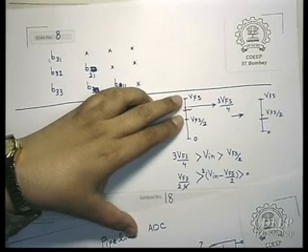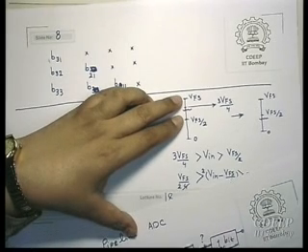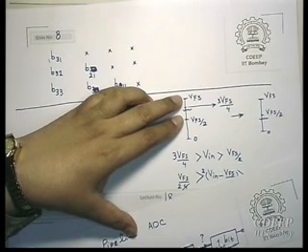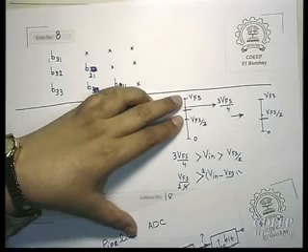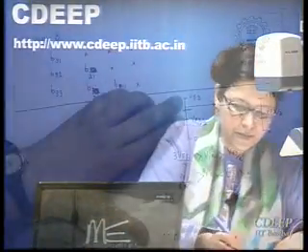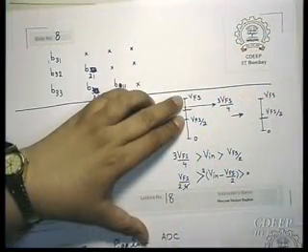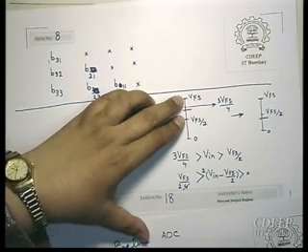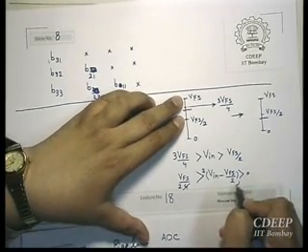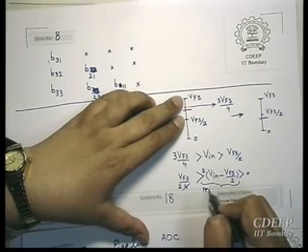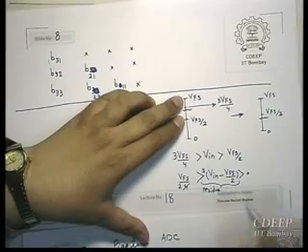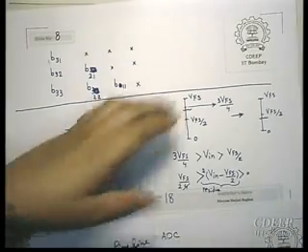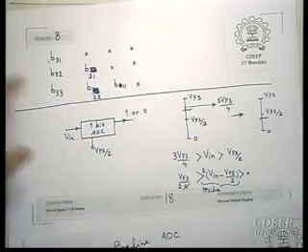Therefore, instead of scaling reference values, I deduct the closest reference value from the input and I scale the residue. This is called residue. Therefore, I can still do the operation with the same scale of the 1 bit ADC. So this is called residue. This is for the case where it was above V full scale by 2.